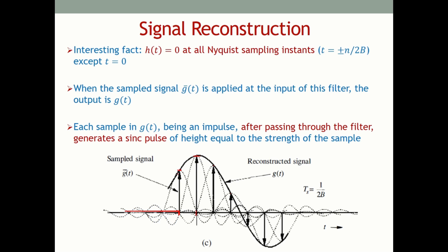So if we add these sinc functions, you can see this one is going down, this one is going up, and when we add them, we get a line like this. This is how we have proved that the reconstructed signal in the time domain is the sum of the sinc functions obtained as impulse responses of these impulses of different amplitudes, right?